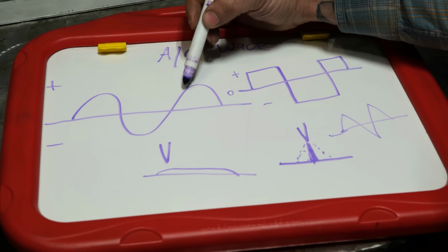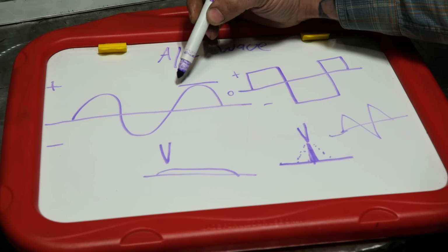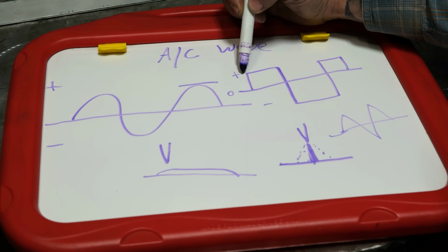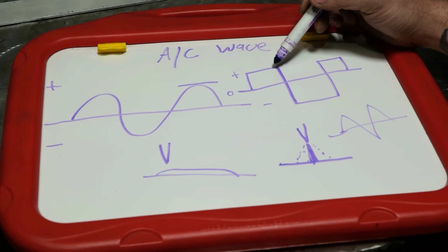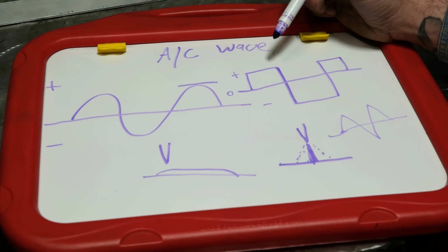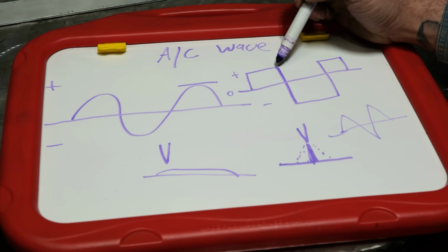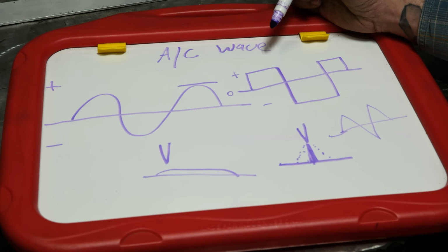So it's pretty easy to see that being tapered like this, because you don't have that flat spot, right here you're inputting less voltage than you are right here. So heat input wise tends to be higher with square wave than with sinusoidal wave, which can be a benefit, because with a 200 amp machine, you can often put more heat into thicker aluminum if you have square wave than you can with a sine wave like that.